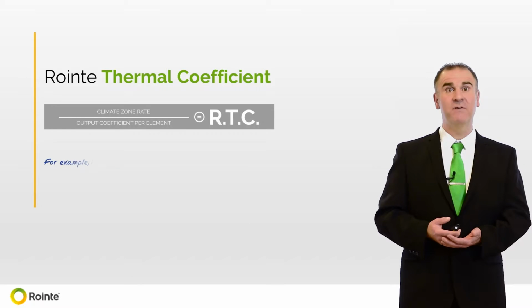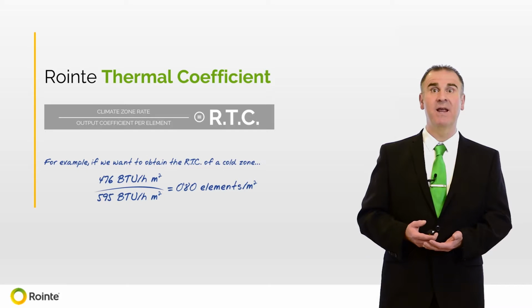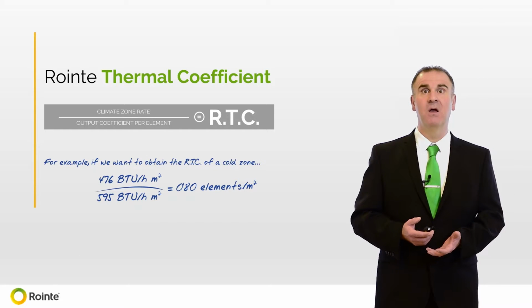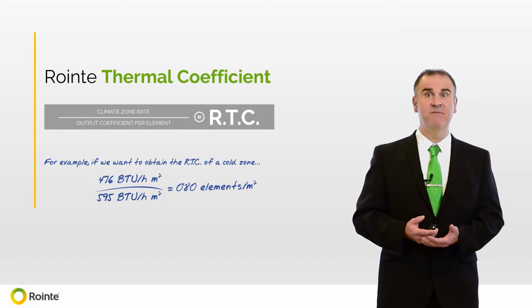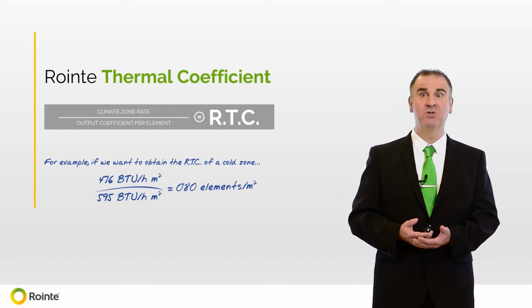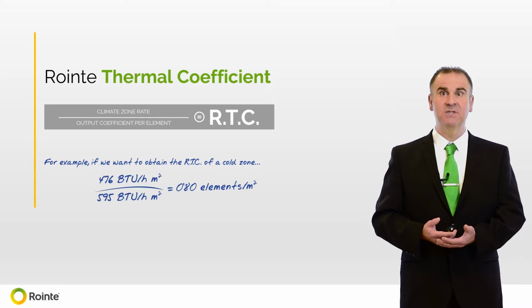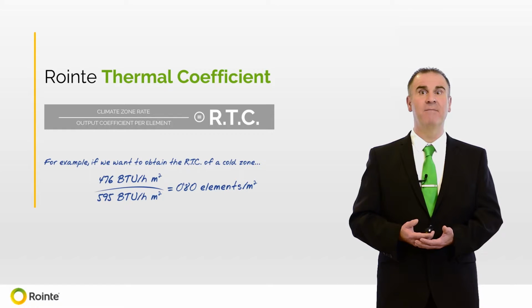The Rointe thermal coefficient is the coefficient developed by Rointe that serves to relate the number of elements necessary to heat a room. The example we have taken is for a property situated in a cold climate zone. We take the BTU value for this zone, being 476, and divide it by the BTU value of one of the Rointe heating elements, being 595. And we end up with a figure of 0.8. This means that 0.8 elements are required to efficiently heat a meter squared area.